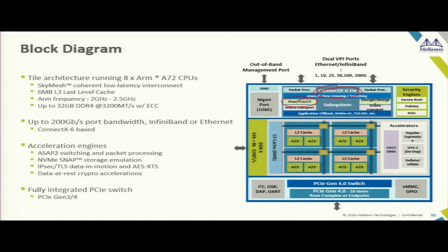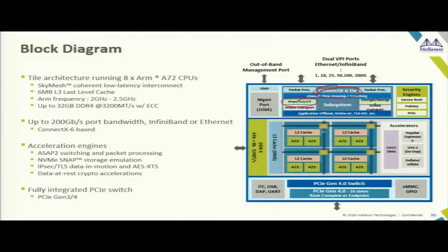So I mentioned, right, the philosophy is network operations should be done closer to the network. When you're doing encryption and decryption, you want to encrypt data on the fly. Why do you want to run that encryption algorithm as C code inside your server? You will be utilizing your cores, and you will be much slower because every data packet has to go through that encryption subroutine. So we implement IPsec or TLS encryption in hardware with state machines. Key management is done through an SSH establishment between the two endpoints in the network itself. So it's like a bump in the wire.